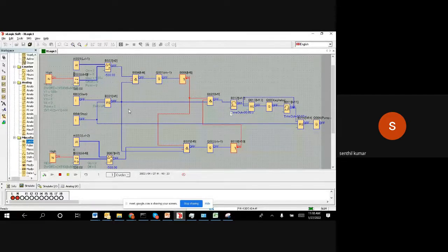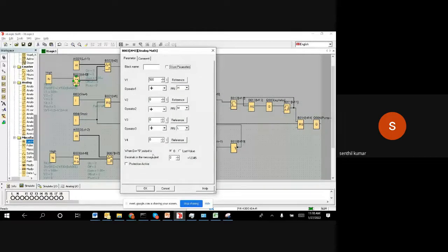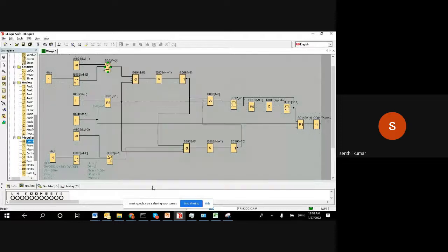So now I'm going to start this. Let me simulate the tank level full. Now my tank level is full. First tank is full. Second tank is full. Because basically, you need to fill the tank to the 1,000 liter. Maybe I can still go offline and move it up to show you the tank level. Maybe I will disable this parameter for more clarity.